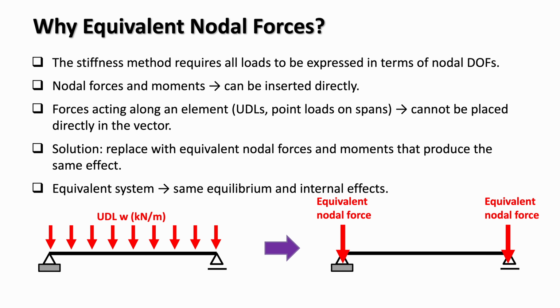Typically, if a concentrated load or moment acts at a location, we would place a node there. But for distributed loads, we cannot add an infinite number of nodes. So instead, we use equivalent nodal forces and moments at the existing nodes of the element. This is the principle behind equivalent nodal forces. We always create a system of nodal actions that is equivalent to the real loading in terms of structural behavior.